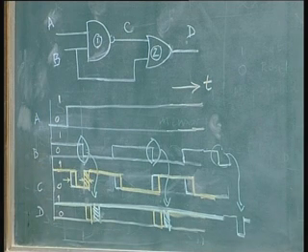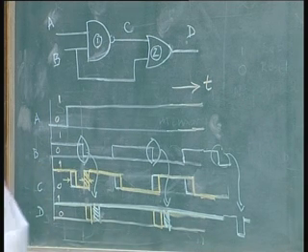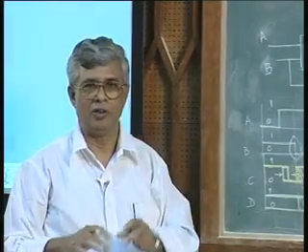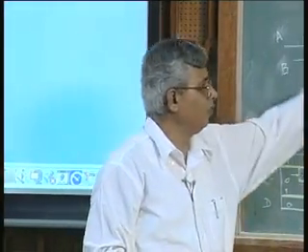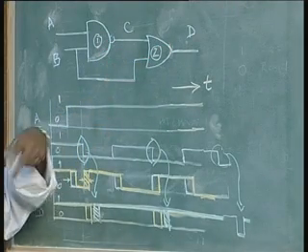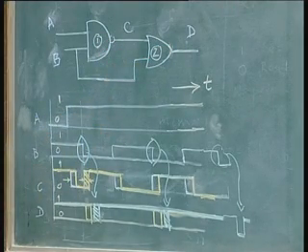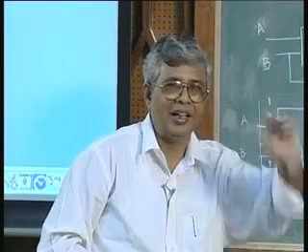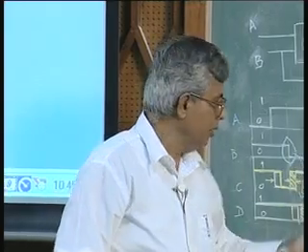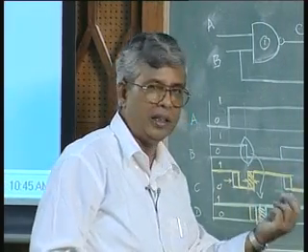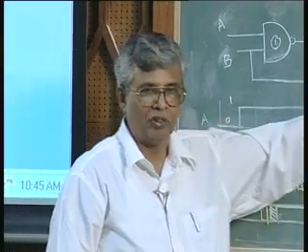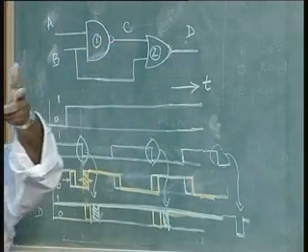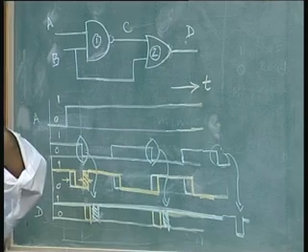So, I can have a positive pulse at positive edge, negative pulse at positive edge, negative pulse at negative edge, whatever is the combination I want, by different types of gates. We have NAND gates, NOR gates, AND gates, OR gates. By combination of these gates, the idea is to use the delay of a gate, that is all there is to it, nothing else. The delay of a gate is used in order to make the input, even though it is always available at the input of the flip flop, reach the flip flop gates, the NOR gates, which do the flopping operation, only briefly.